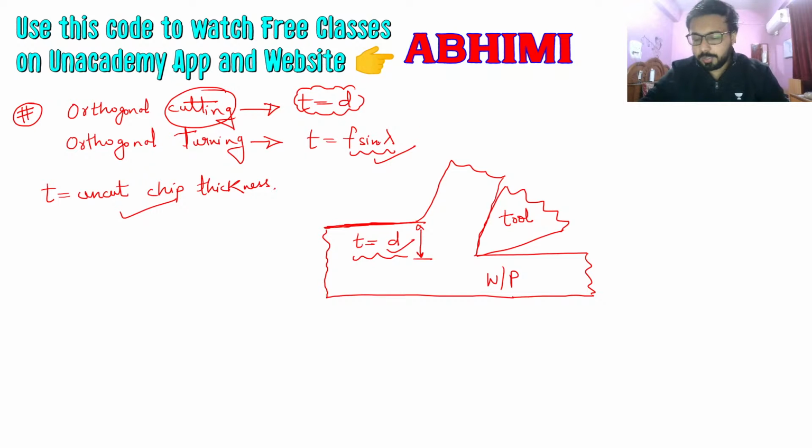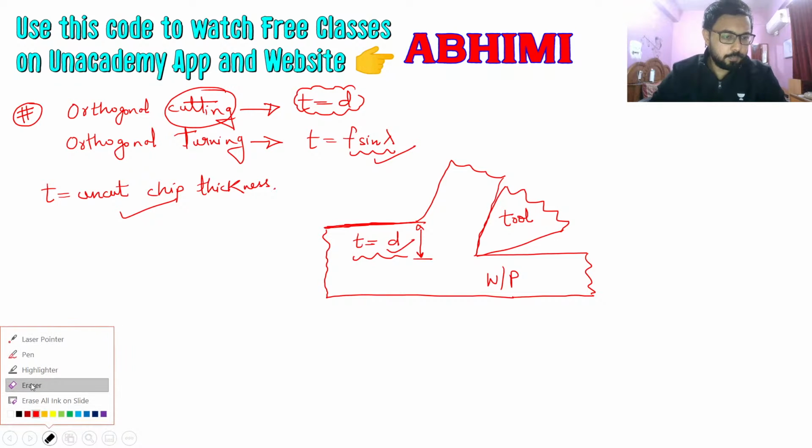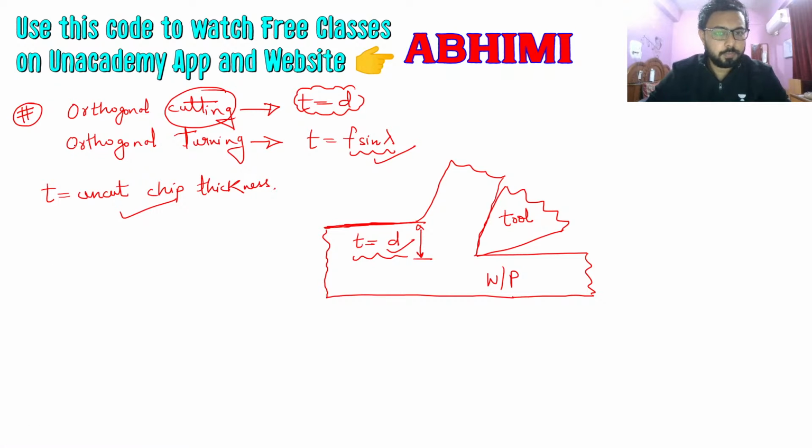What we know about here is not orthogonal turning, that should be only turning, because for orthogonal turning what happens... I think I have to just write it down here. So for orthogonal turning, this will become t is equal to f because lambda is 90 degrees. So simply for turning, the uncut chip thickness is equal to f sine lambda.